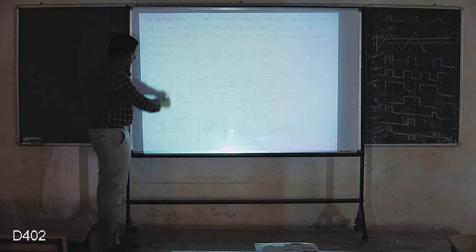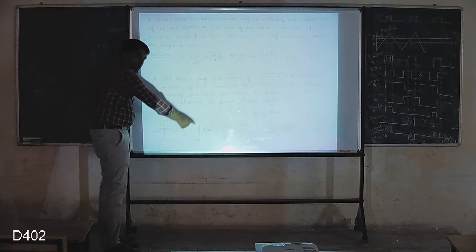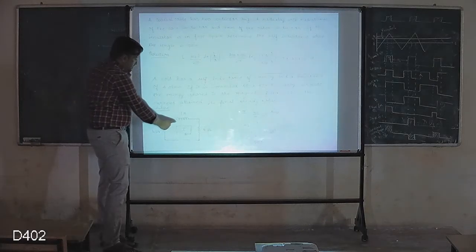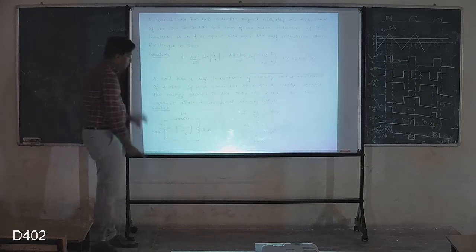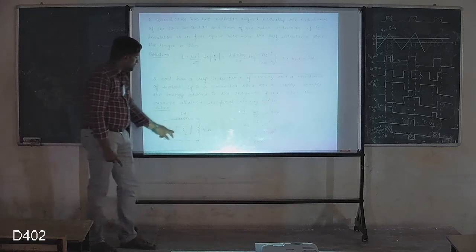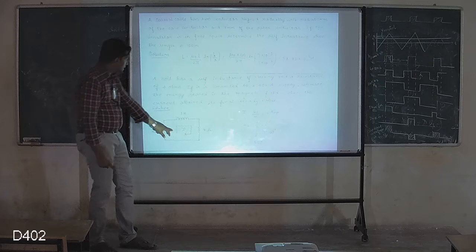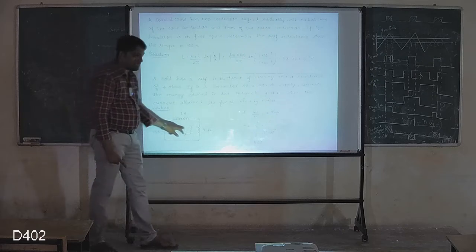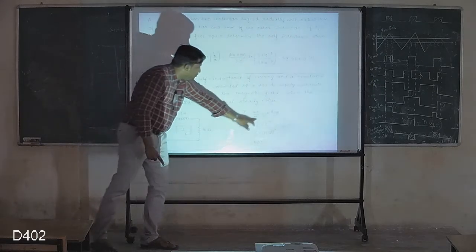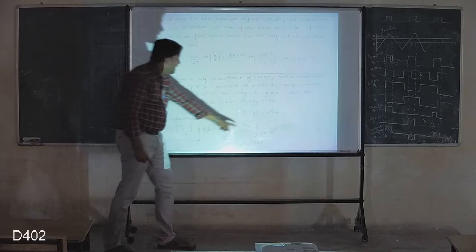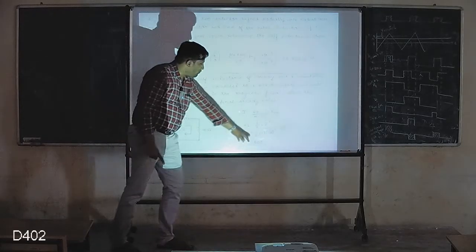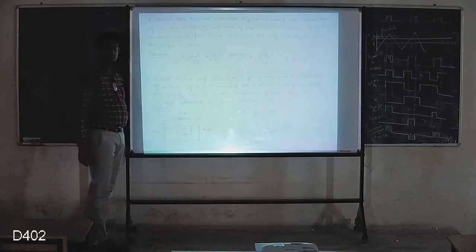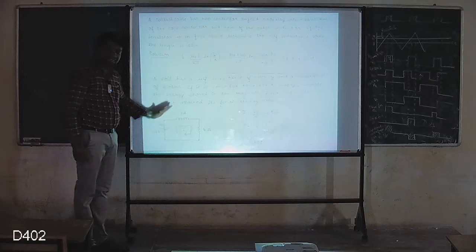So with the help of the given data, I draw a circuit which has a self inductance and a 4 ohm resistance with a 40 volt battery, and a current is flowing here. To estimate the current, it is given by 40 by resistance. The resistance is 4, so 40 by 4 happens to be 10 ampere. So L is known, I is known, find energy stored. Energy stored is equal to 50 joules. So the answer is 50 joules of energy will be stored in such a circuit.